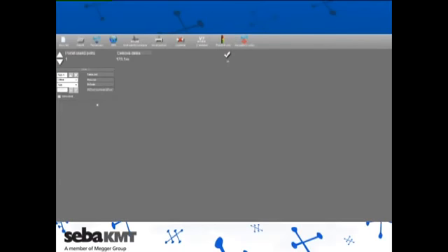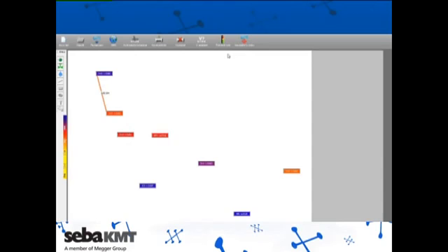Then we can enter the pipe parameters of the individual pipe sections: the length in meters, pipe material and diameter. We enter the pipe parameters for all remaining pipe sections of the measured network in the same way. We select the loggers between which we want to define the pipe section by clicking the mouse and once again entering the length, pipe material and diameter.